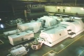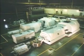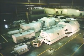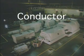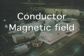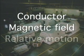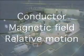All generators use induction to create an output voltage. When the output of a generator is connected to a circuit, the induced voltage causes current to flow through the circuit. There are three requirements for inducing voltage. First, a conductor must be available to carry current. The second requirement is a magnetic field. Third, there must be relative motion between the conductor and the magnetic field.